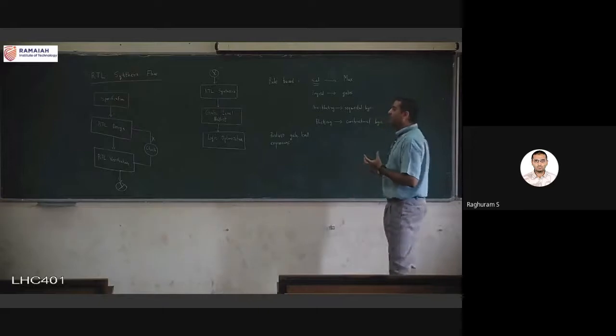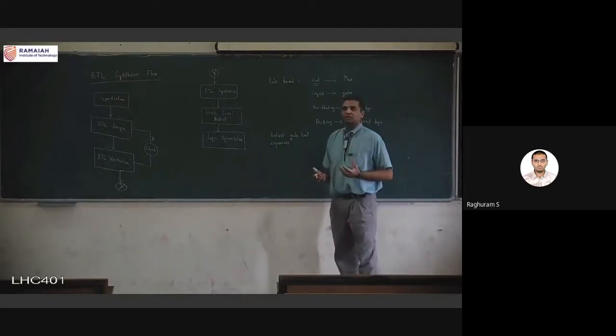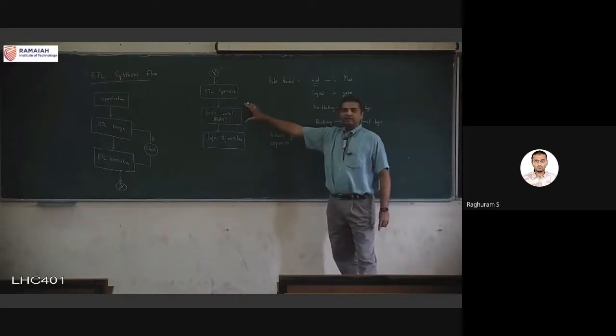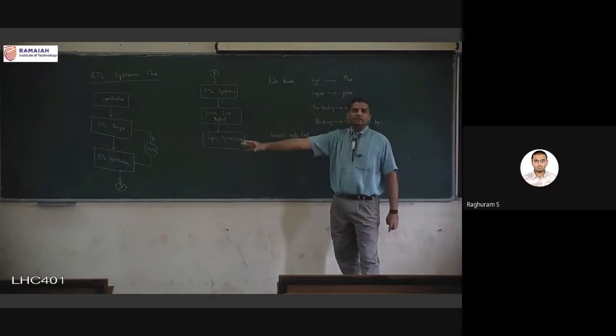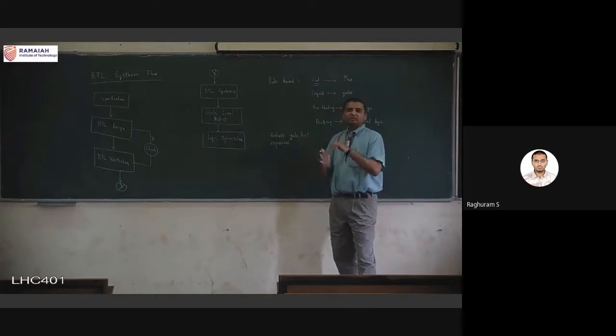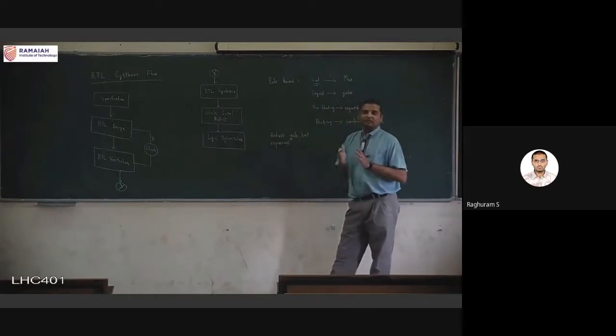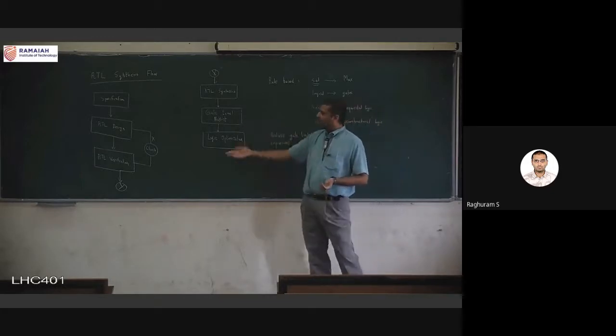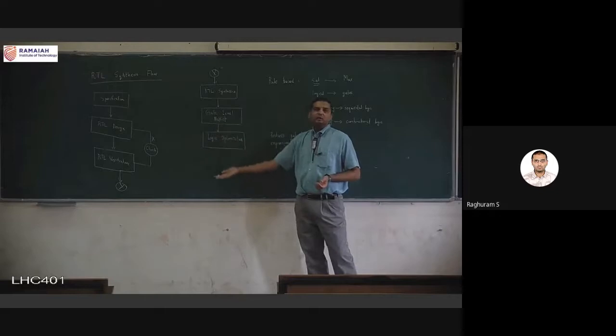Suppose I have some function, in this stage I have the gate level netlist, but it has some 25 terms in it. Suppose I can reduce that to a function with just say 18 terms, because the other terms were either redundant or they were in such a way that they are never coming into the picture, etc. All those are made into an optimized form at the end of this stage. So this is the final gate level description.